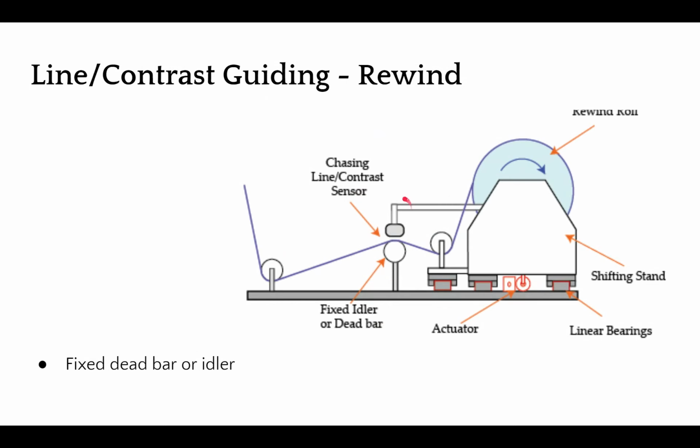Ideally, in this winder or rewind, it's kind of the same thing here, we want to put this as close to the winder as possible. That would be the ideal location. If you have a roller that is going to take care of the diameter variations, then putting this sensor as close as possible here would be the ideal location. Farther away, again, we're adding delay to the system.